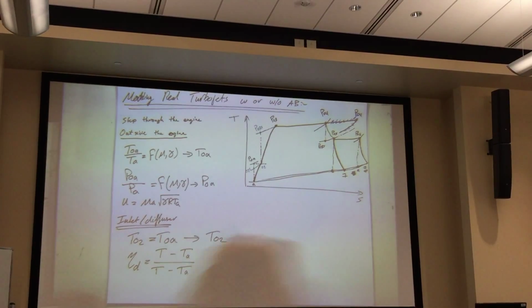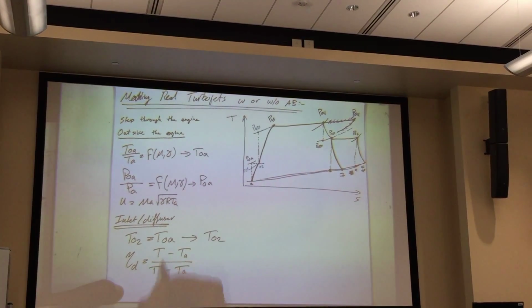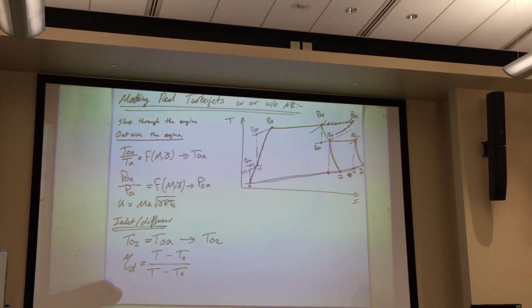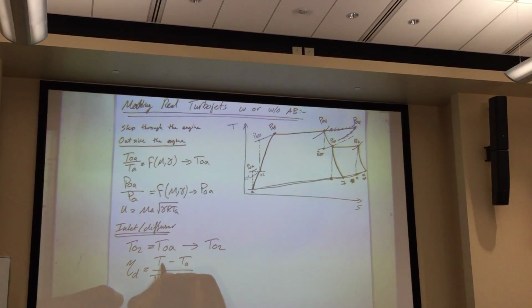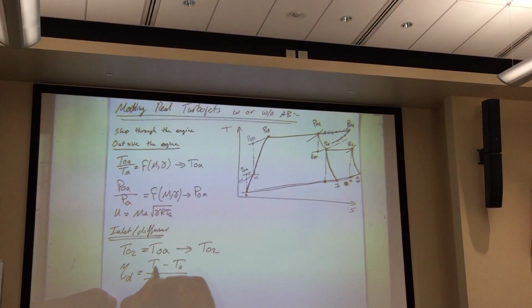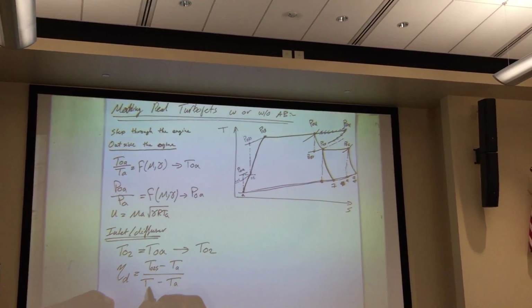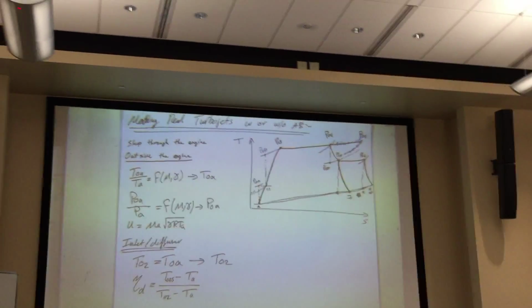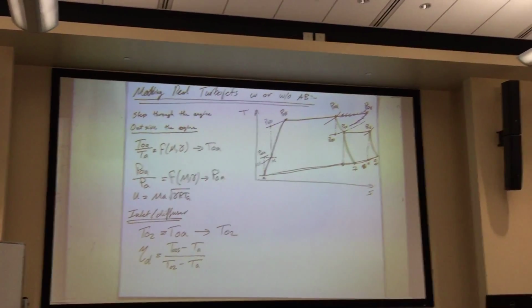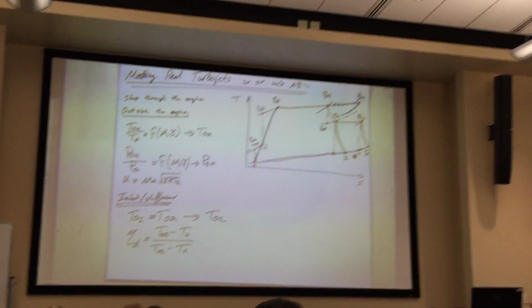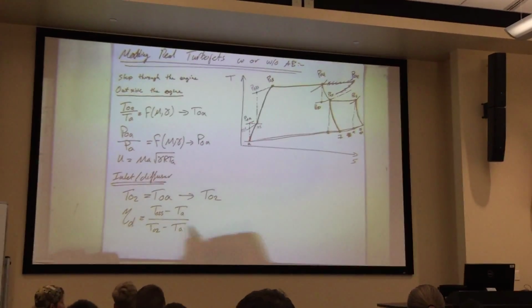So if I did O2 here and O2S here, what's going to happen? Okay, very good. So this is O2S, and this is O2. Isentropic goes in the top. And the same thing on the other side, by the way. So I'm going over this so you make sense of it as you go through. If your efficiency is more than 1, it doesn't make any sense.